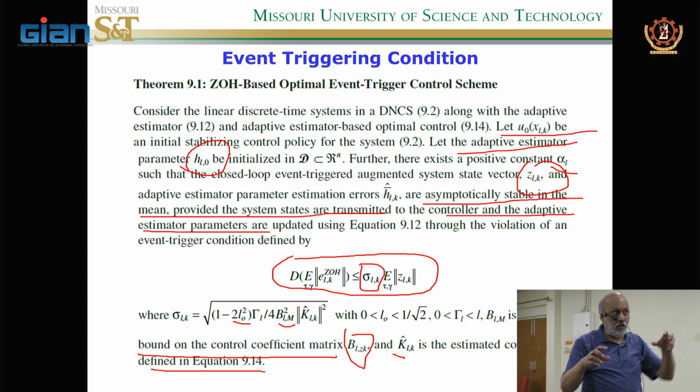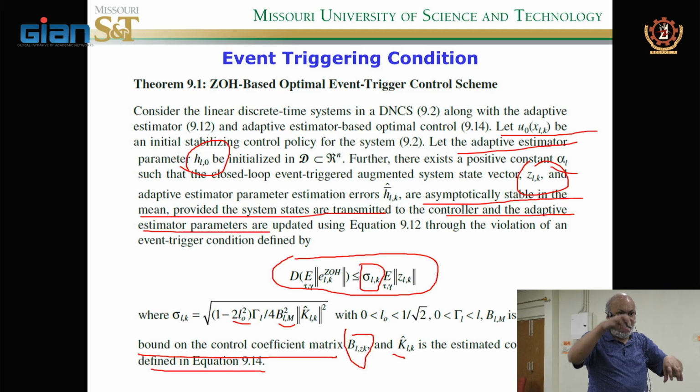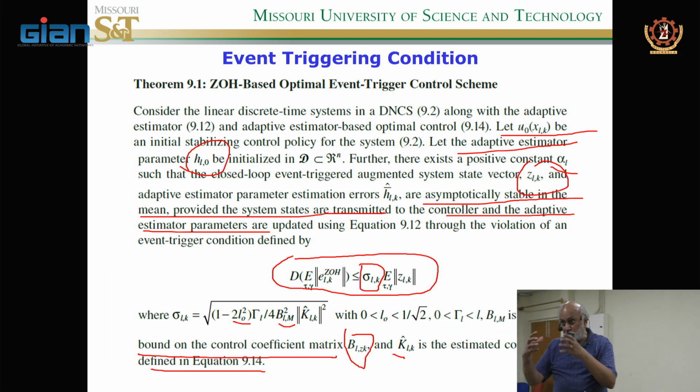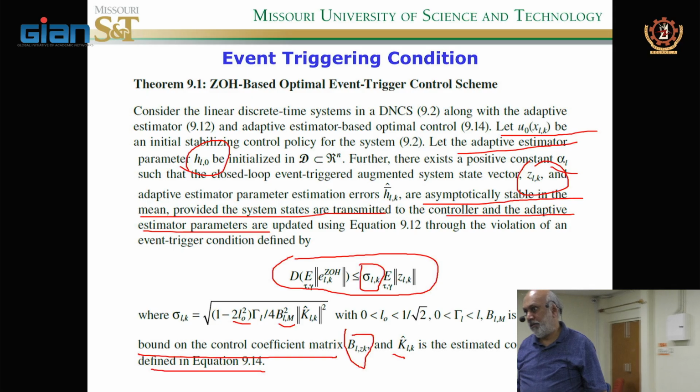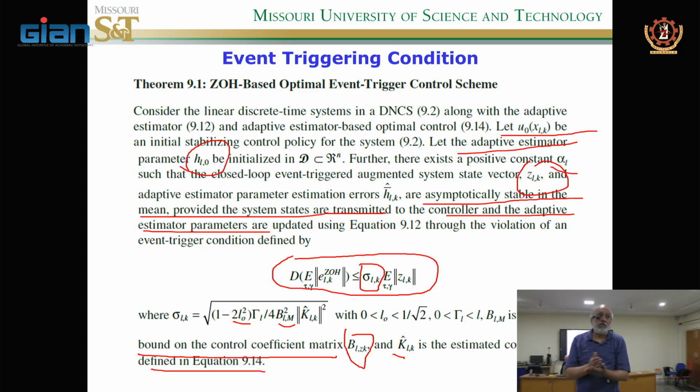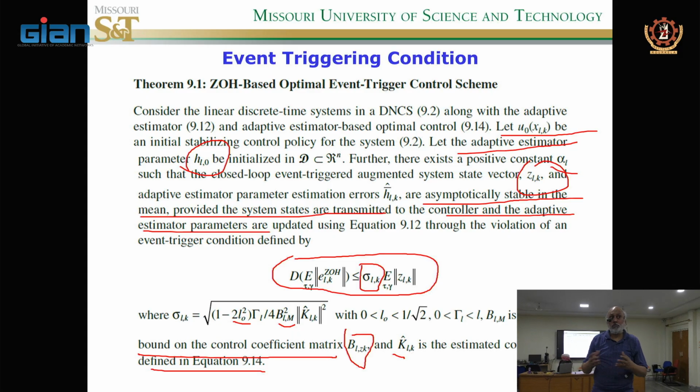Automotive systems, if you look at commercial automotive systems, they have a CAN bus. Under the CAN bus you have diagnostic modules, engine, final drives. They're all sharing that CAN bus, and they all transmit their status information and any maintenance information. All that information goes through that bus, and it is shared and stored in a memory. So they all use the same bus, and there's a potential that can lead to congestion.